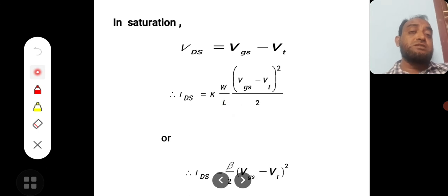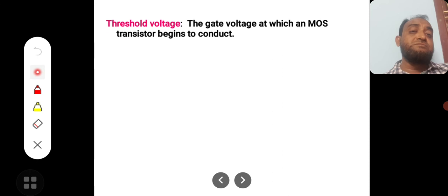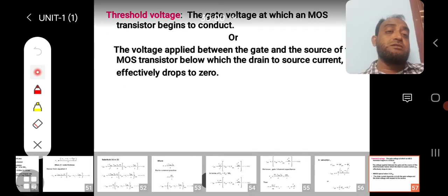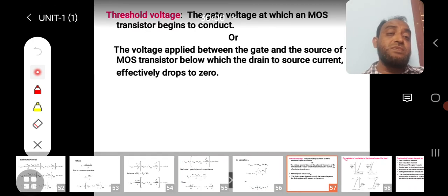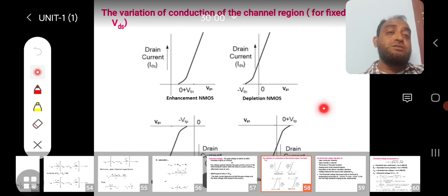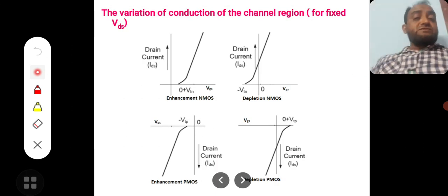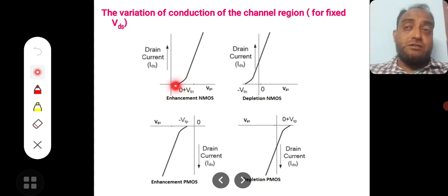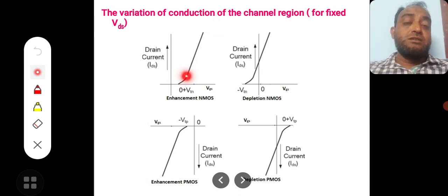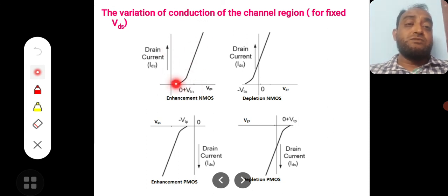This is the saturation current. Similarly, as we wrote in terms of beta and C naught, we can again write all the terms in terms of capacitance. Now these are the electrical characteristic curves of the MOS transistors. If it is an NMOS enhancement mode transistor, its conduction will start at threshold voltage VT and extend like this. It's the non-saturation region, and this is the saturation region. This is drain current, and this is gate voltage. The input characteristics.